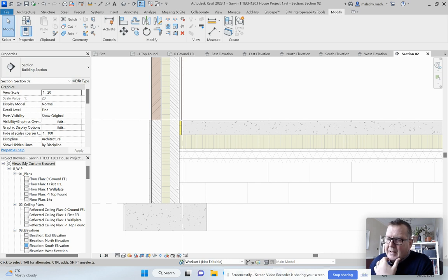It all depends on where you're actually building these and where the groundwater level is and various things like that. So if the groundwater level was high here, you might do a solid wall down there because obviously the water would get in and probably rot that insulation, or it would act as almost a siphon to bring the water up further, and you don't want that to happen either.